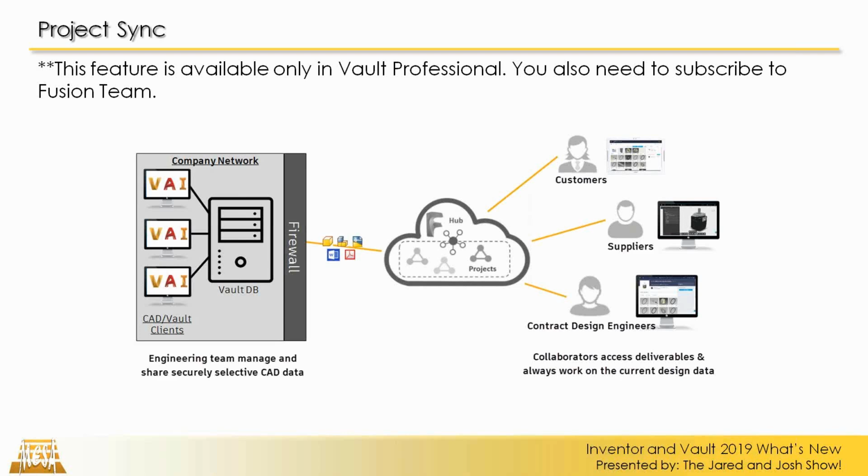Now, two caveats with Project Sync right off the bat: Vault Professional only, and you have to have Fusion Team. But what Project Sync is going to allow us to do, it's going to be a replacement of Buzzsaw with some enhancements. So we're going to be able to take our Vault data, create folders within our Vault hierarchy and publish those out to a cloud directory inside of Fusion Team.